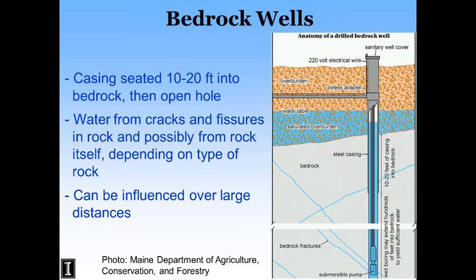So a bedrock well is basically the same type of drilled well as a sand and gravel well, except you don't have a screen at the bottom. And the reason is, you know, bedrock is solid. As you drill through it, you might encounter a fracture or two, but you don't put casing all the way down to the bottom of the well. You put a steel casing in generally, and you seat it somewhere in the rock so that it's solid. But then the rest of it, from this point on, is an open hole. And that allows all the fractures to be connected directly to your well, and so water can flow through those fractures when you start pumping your well and replenish your supply.